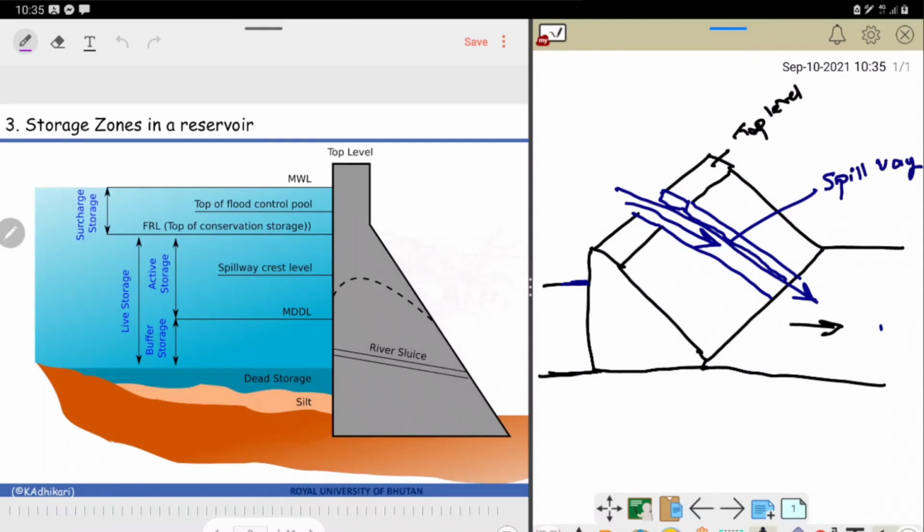So we are going to spill out the excess water. That is the spillway. And if you just think about it, it is just a drain, a large drain to get rid of excess water. So here in this diagram, now you can look over here. Here I have drawn this. This is what we call the spillway. Although I am not able to give you the three-dimensional perspective, when it is constructed, it is constructed with a curve in mind, so that water can flow smoothly, not like what I have drawn. It's in a curve shape, like it is shown here.